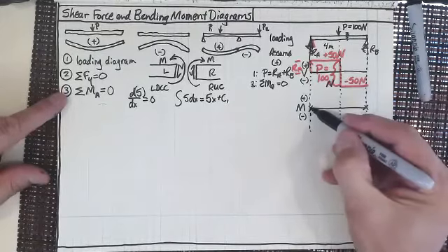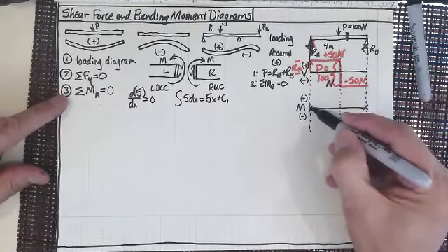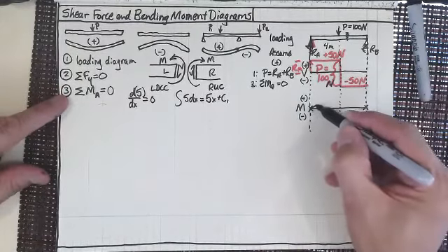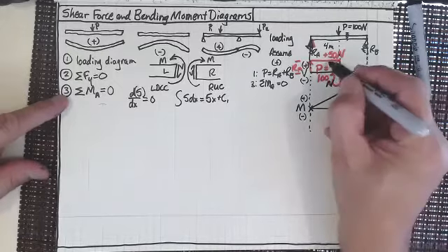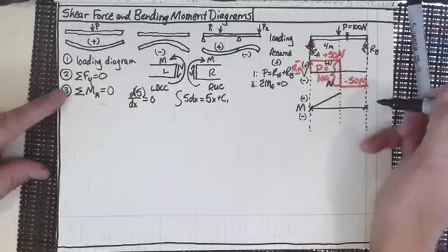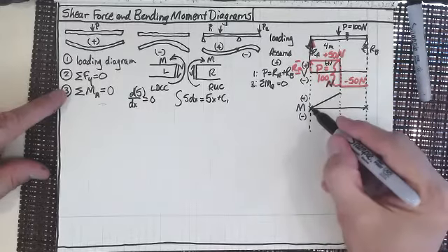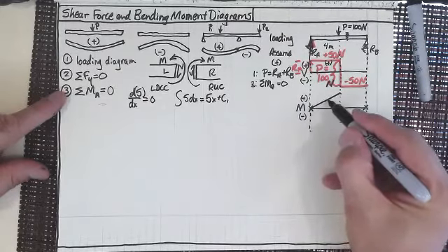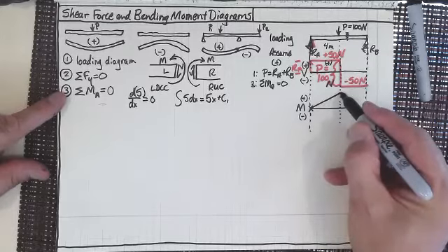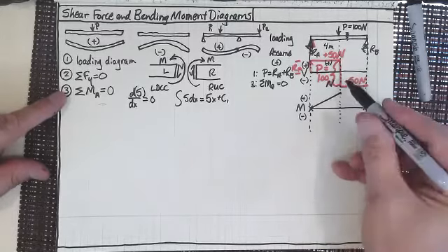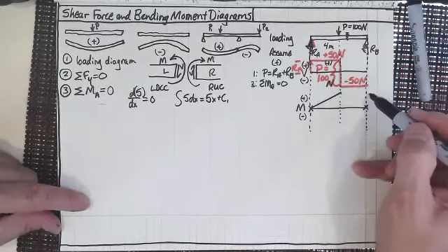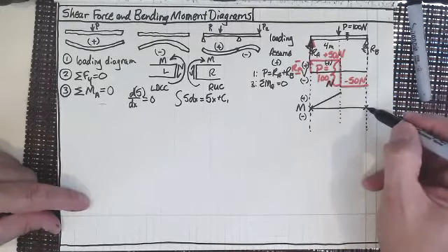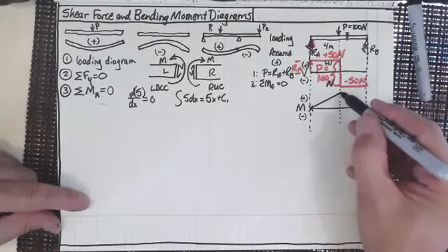We know that we're going to have a slope that is 50 newtons per meter, and it's positive, right? Well, doesn't that look like a line with a 50 Newton per meter slope going up there? We know that the slope has to be negative 50 newtons per meter coming down. So, well, it's 4 meters both ways.